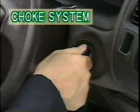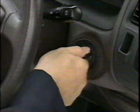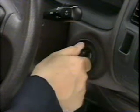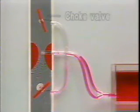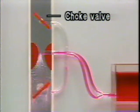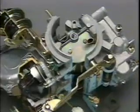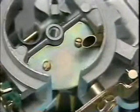This brings us to the choke system. Without a choke, it would be difficult to start the engine in cold weather. The choke valve is provided above the nozzle to decrease the amount of intake air during starting. In this way, the choke helps start the engine and improves drivability. The choke valve is located in the primary side air horn.